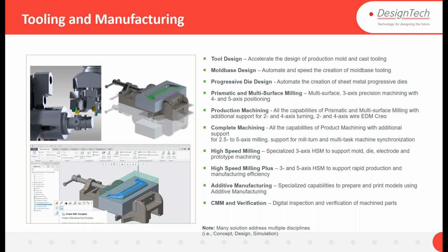If you are using that kind of standard, you can use that extension to bring the standard mold base inside that environment. So you can do complete tool design where you can extract the core and cavity for plastics or for any other casting component. You can also use the progressive design environment where you can use sheet metal for progressive.